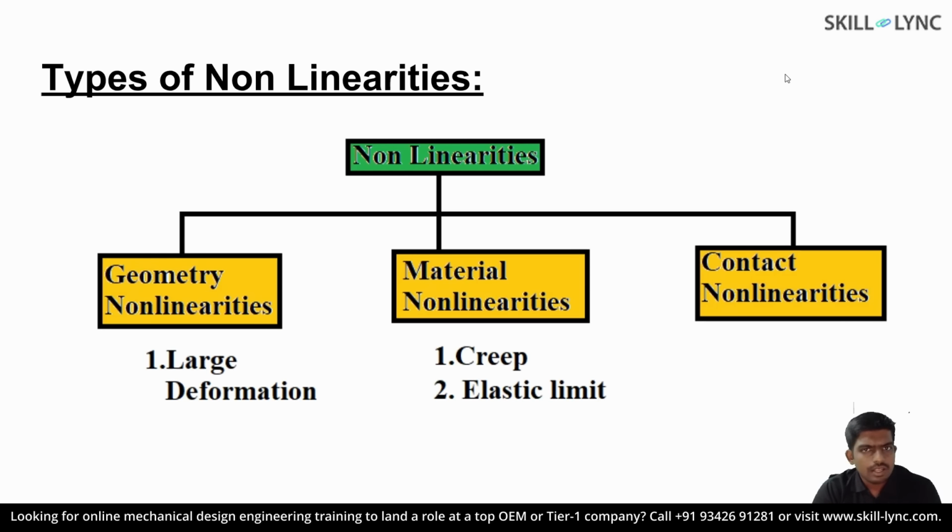Now, secondly, beyond the elastic limit, any metal will move into the nonlinear region, while nonmetals can behave nonlinearly within the elastic limit. And finally, apart from geometric and material nonlinearities, we do have contact nonlinearities, which are caused by the changing status of the contacts throughout the simulation.